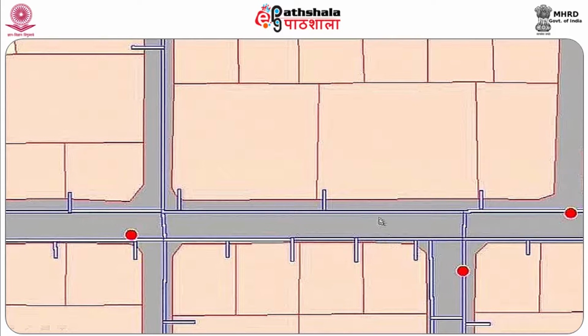I can say the total width existing is 15 meters, say about 50 feet. I want to make it a 60 feet road, maybe 5 feet this side and 5 feet this side. For the particular center line, we can give instruction to the system to demarcate or draw a 30 feet buffer from here to here. This 30 feet buffer from the center line will definitely crisscross these land parcels.